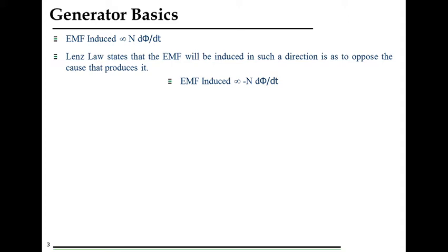So in India we have a frequency of 50 Hz. So here f will be 50, and suppose we have a thermal power plant in which the generator has 2 poles. So here Ns will be equal to 120 into 50 divided by 2. So this comes to about 3000 rpm. So in an alternator that is running at 3000 rpm, this is running at synchronous speed.